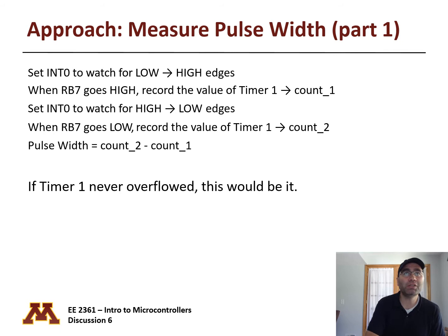Okay, so here's the approach. We set the timer. We set the int0 external interrupt peripheral. We already did that, so it's going to detect the high edge, right?